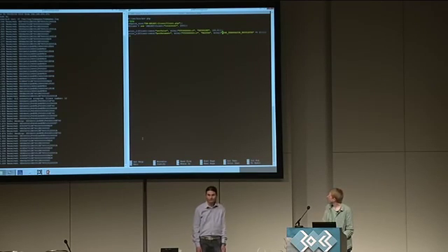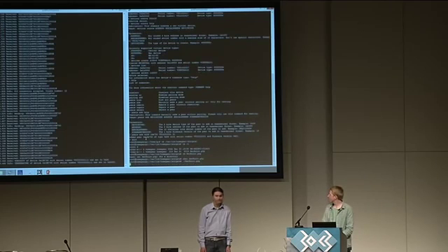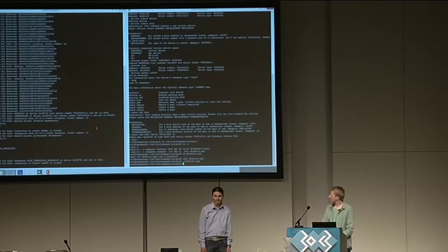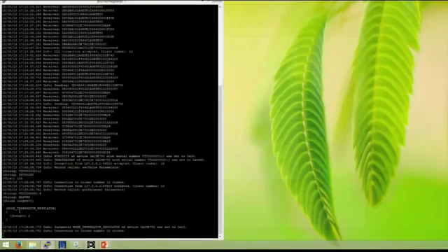Okay. Now, we are just executing our script. On the left side in the log, you can see that HomeGear received both RPC packets. Now we need to wait a little bit, because it takes 2 to 3 minutes for the thermal control to send a wake me up packet, and then HomeGear starts sending. In the meantime, I am showing you what you will see.